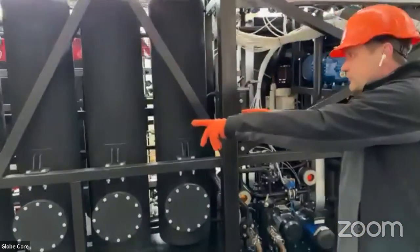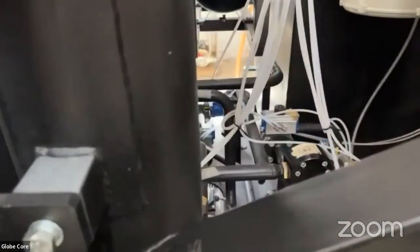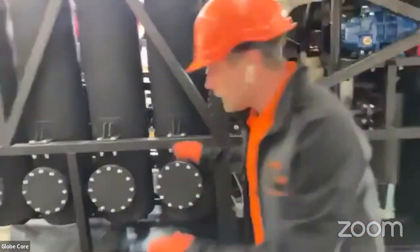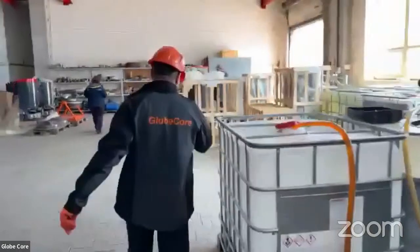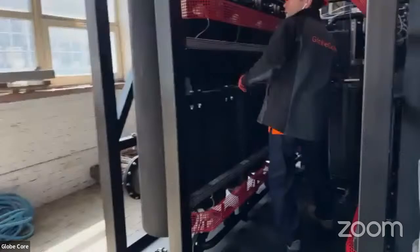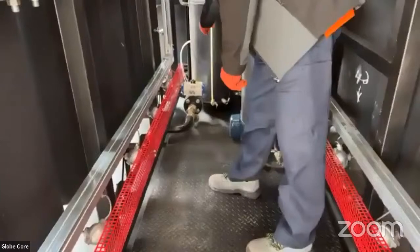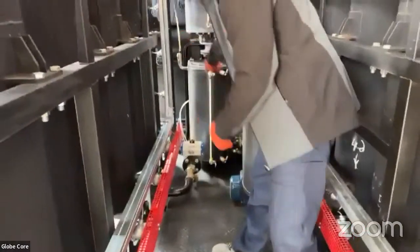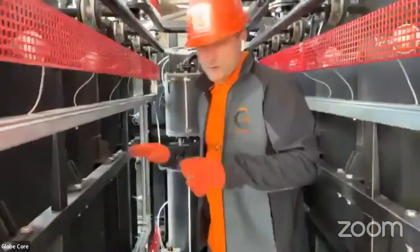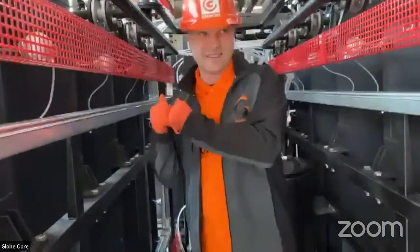So, regeneration columns, gear pump to take oil and to push it through the sorbent. Again, at the bottom of the columns, we have the manifold which goes to the intermediate tank, and from the intermediate tank, oil is passed to the fine filter. So the principle is the same as in the previous, the simplex unit.